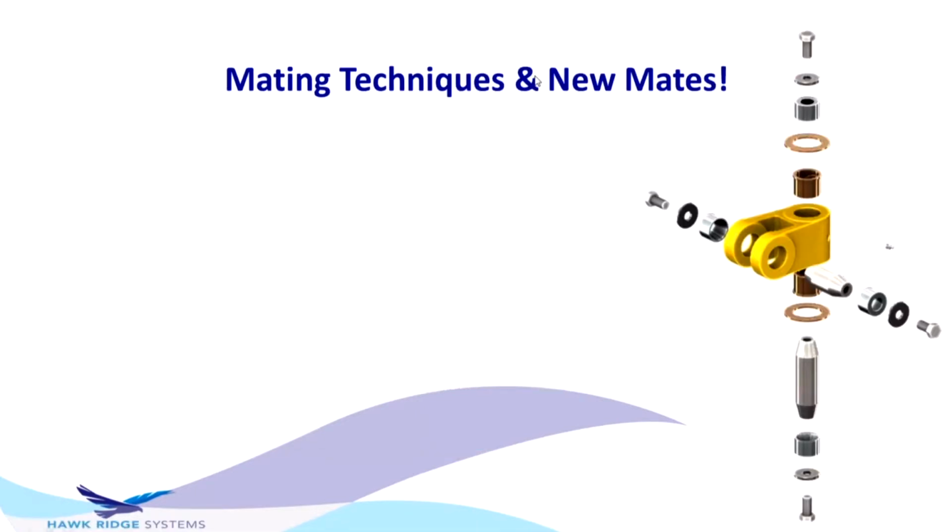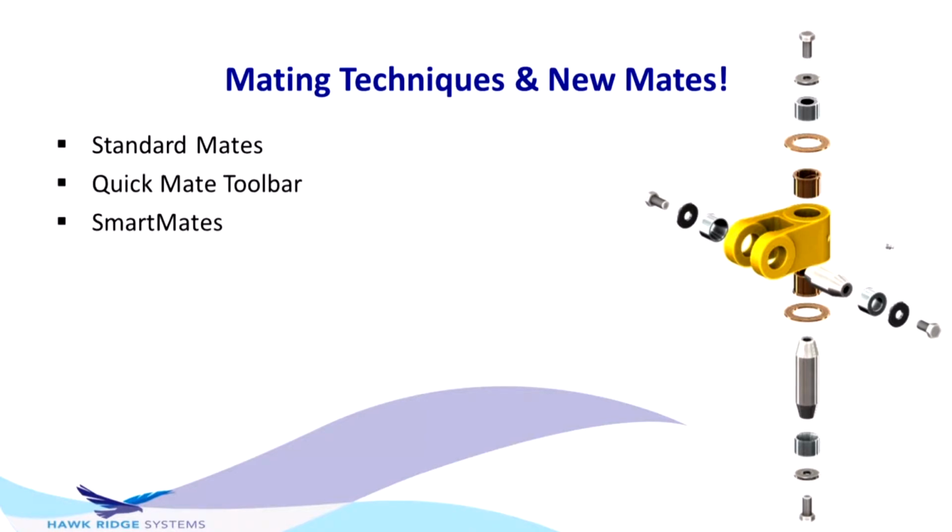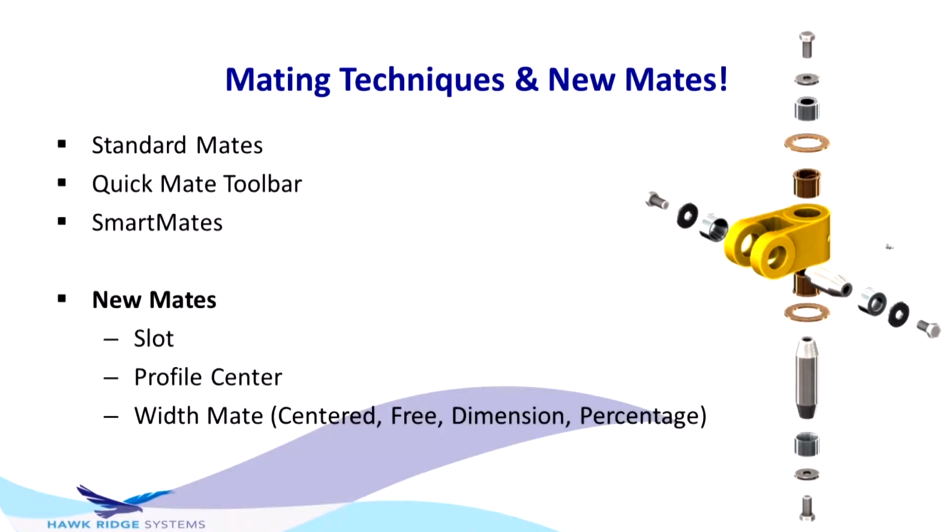So here we want to talk about mating techniques and also introduce new mates. We'll talk about standard mates, the quick mate toolbar, Smartmates, and then also introduce the new mates, things like the slot, the profile center mate, and the width mate. If you've used the width mate before, you'll notice it's not exactly new, but they've introduced things where it's always automatically centered, but you can now add a dimension as well as a percentage.